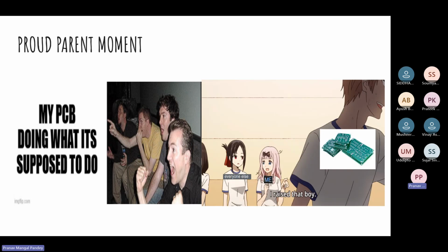You had not stress tested it initially. It worked when you used it single handedly just to check if the board was working. You find out the board is live, so you are good to go. You put it on the main system and then poof, it goes off. So stress testing your boards is where you get to find out what the issues are, especially when you talk about the traces in the copper size, the wires which go from one point to another.